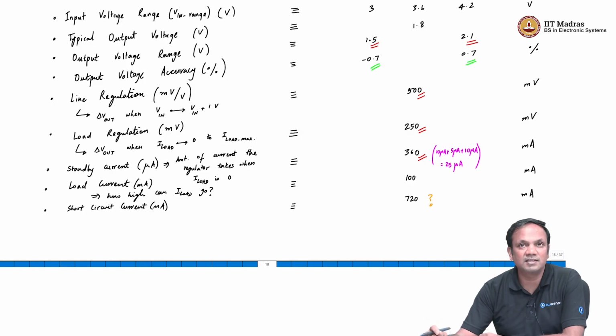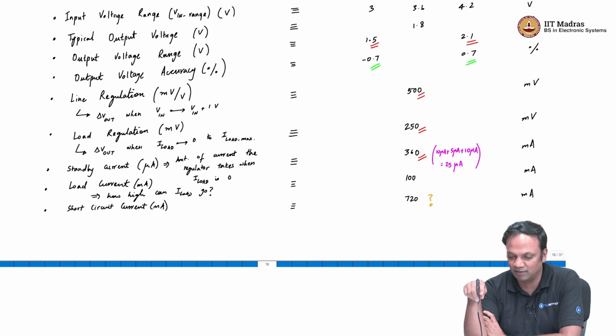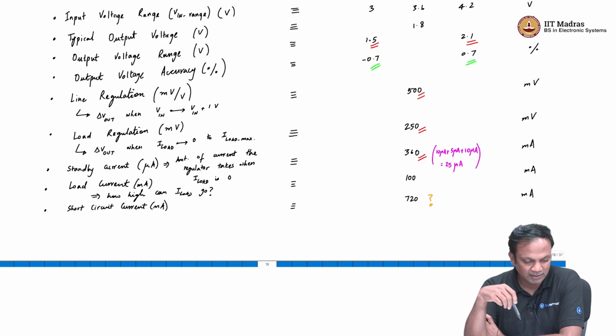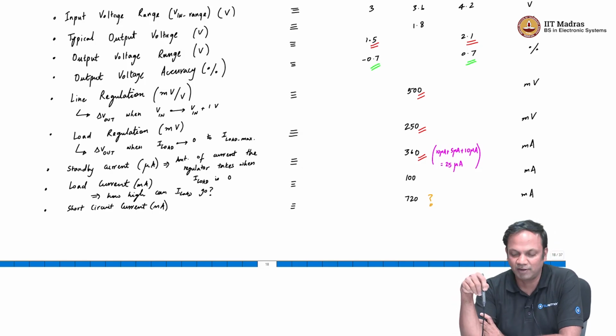So, what was 360 milliamp and turning out to be a very large problem unless we increased the resistor, in which case load regulation would have suffered, has been addressed through the use of the amplifier. Now, with the amplifier we were able to decouple the standby current problem from the load regulation problem. The standby current is now down at 25 microamp, and because the output current is now being supplied by an amplifier as opposed to being supplied by a resistor, the load regulation will also be much better.